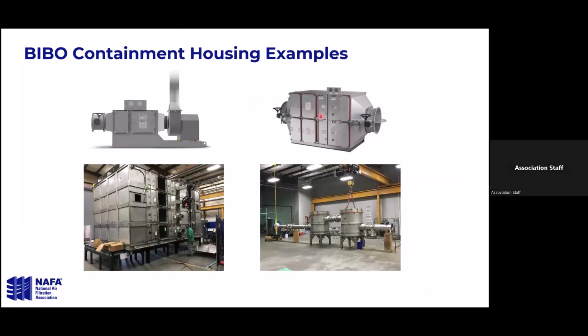This housing on the top right, you would see more for a biological application. You'll see on the transitions here on each side, there's decon ports. The reason those decon ports are in there is generally in a biological application, before you do any filter testing or filter change out, you're going to want to decon that housing to kill whatever's in there.